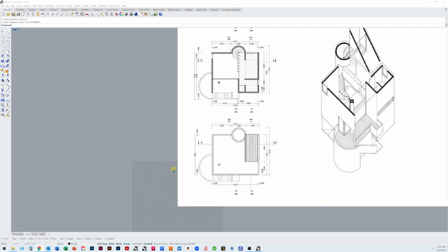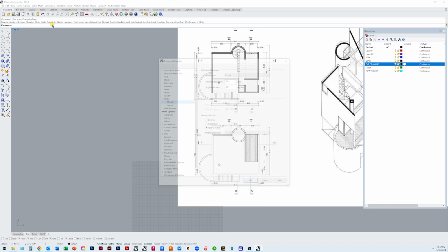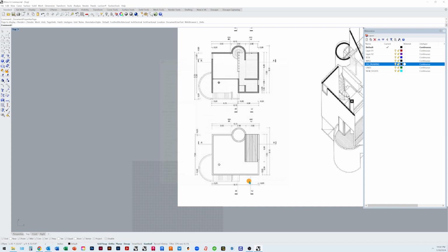The easiest way to do that is to use the scale command. So first you do want to make sure that you're in the right units. Just like we did on the very first day, let's go to our units, make sure we're in inches, make sure we're in feet and inches. You can change our precision down to 1/128. Hit OK. So we have our units set up.